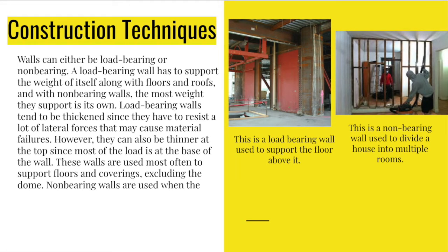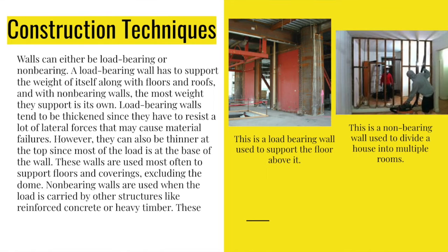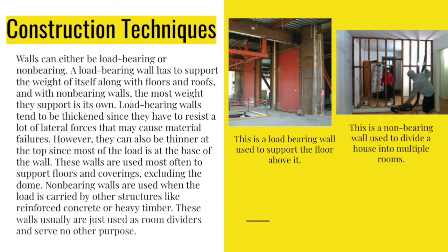Non-bearing walls are used when the load is carried by other structures, like reinforced concrete or heavy timber. These walls usually are just used as room dividers and serve no other purpose. This is a load-bearing wall used to support the floor above it, and this is a non-bearing wall used to divide a house into multiple rooms.